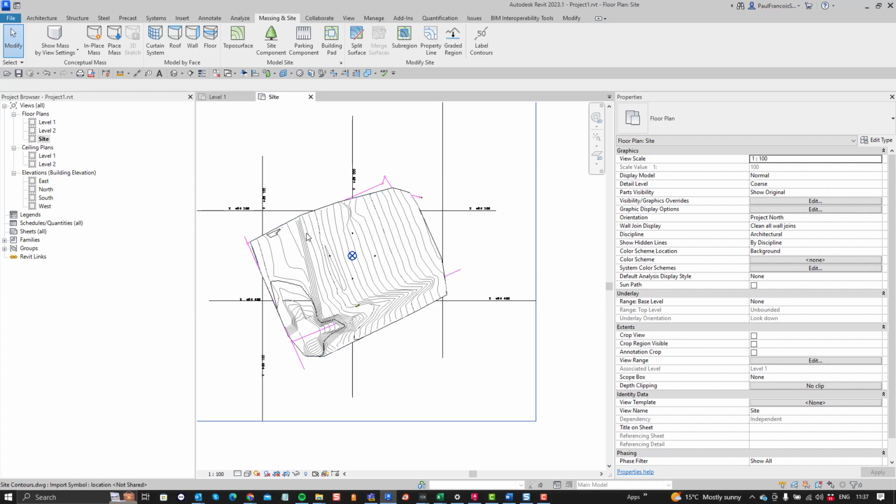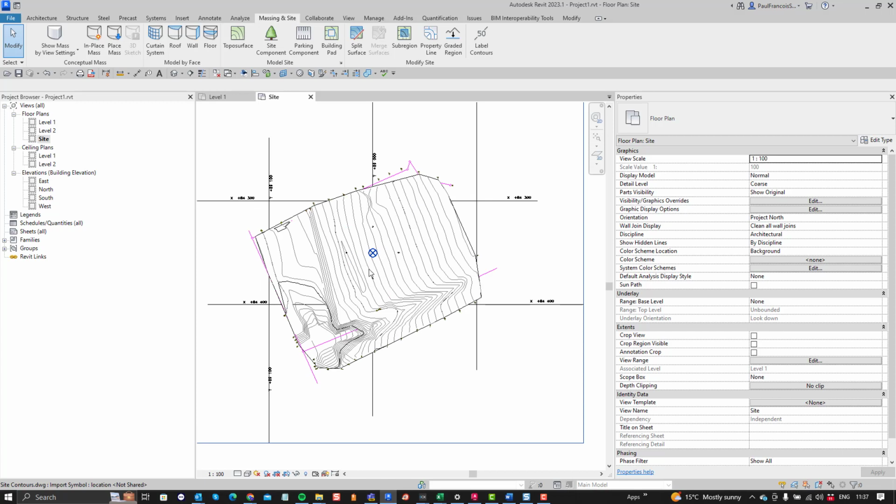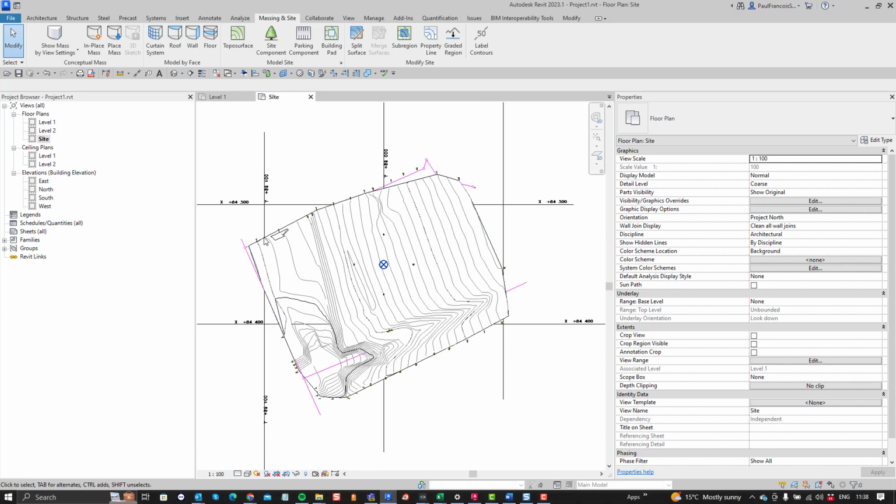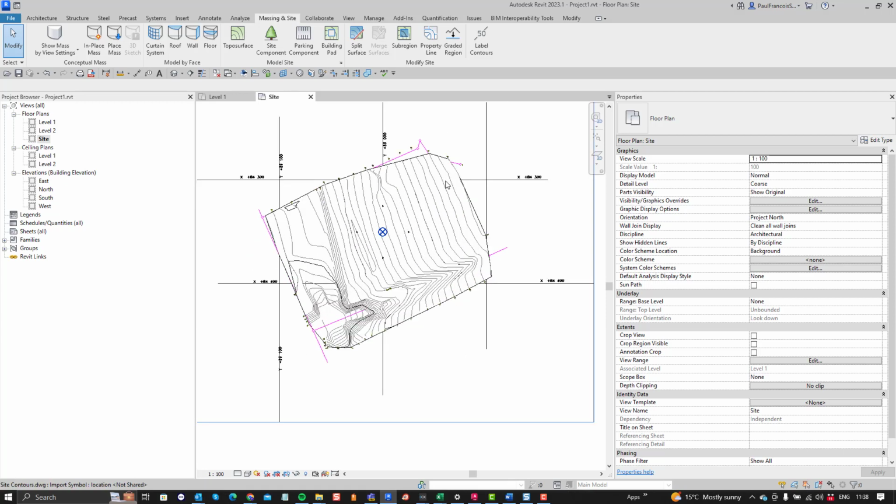If you create a CAD file like that, then it's very simple within Revit. Simply bring it in center to center so that it's in the middle of the drawing. So the X and the Y, we're basically lying that it's not far away from the origin. But in the Z direction, in the elevation, we've got the true elevation of that site.